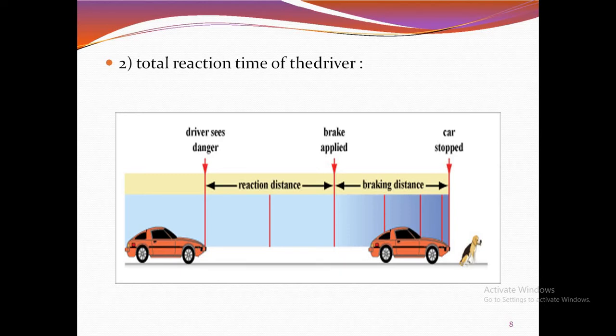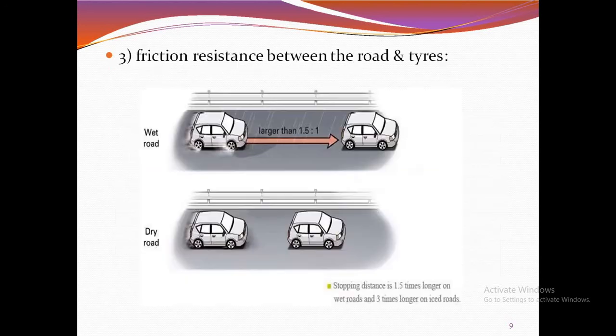Perception time is the time required for a driver to realize the brakes must be applied. It is the time from the instant the object comes on the line of sight of the driver to the instant he realizes that the vehicle needs to be stopped. Brake reaction time depends on several factors, including the skill of the driver, the type of problem, and various other environmental factors we need to take into account.